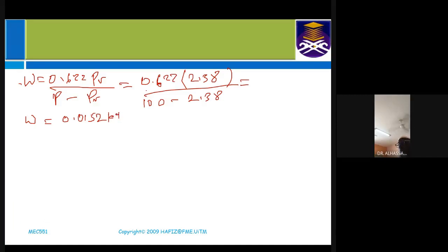So, kilogram of water vapor. Whenever you see V, we normally express it in kilogram of water vapor per kilogram of dry air. V is for water vapor, A is for dry air. So that is the unit. All right, now the enthalpy of the air per unit mass of dry air.